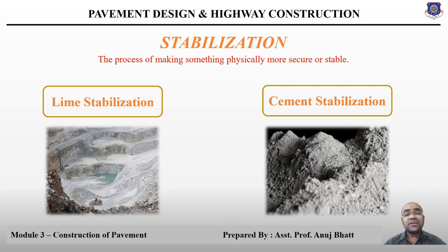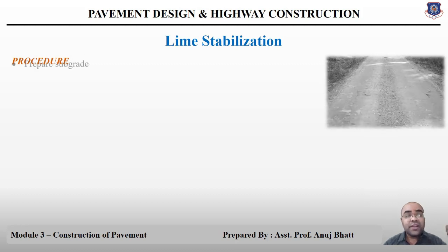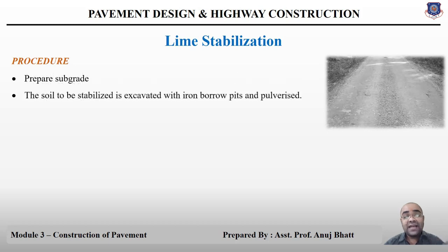Let's move on to the construction procedure of lime stabilization. When you start the construction, the first step is the preparation of the subgrade. After preparing the subgrade, the soil that has to be stabilized is excavated from borrow pits and then pulverized.